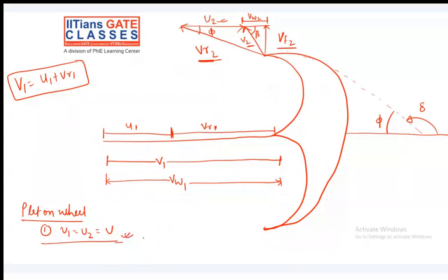Okay. And here we have no nozzle angle at the inlet. Yes or no? So alpha is equal to 0. This we have seen. Similarly, theta is equal to 0, and vf1 is also 0. Why? Because the velocity has no axial component, right? All of the velocity has a tangential component. So can I write down that v1 itself is vw1?